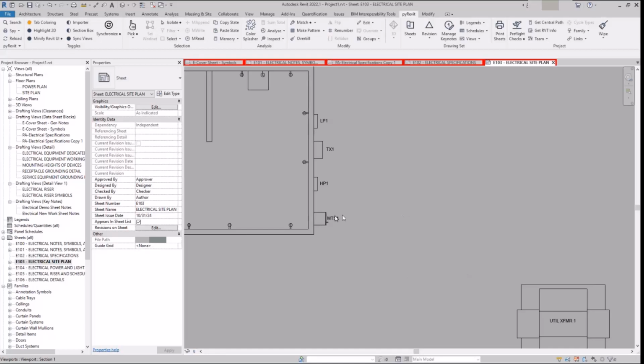How do you want me to go from the MTS? How do you want me to mount the MTS? What conduits do I need? What conductor style do I need? THWN, XHW, USE, so on and so forth. Now I'm throwing out all this random information, but these are the questions you're supposed to be asking from a contractor's perspective. How do I physically build this?